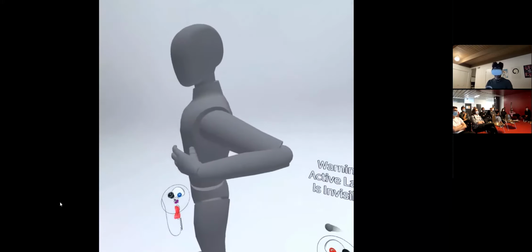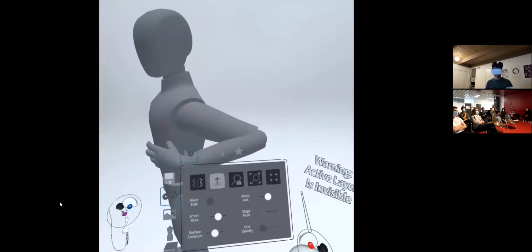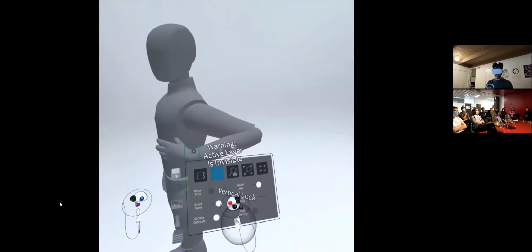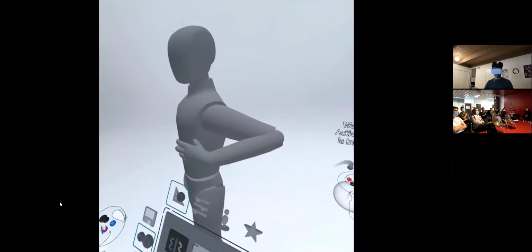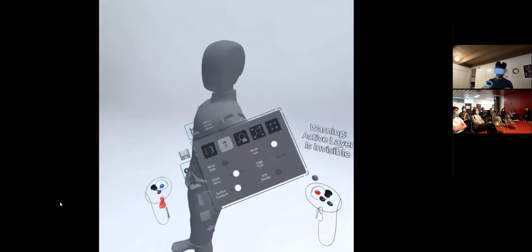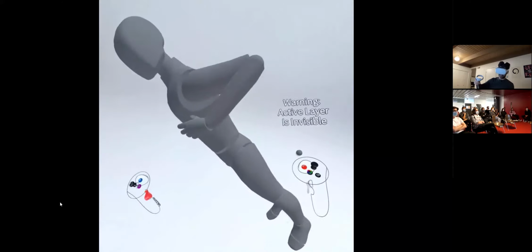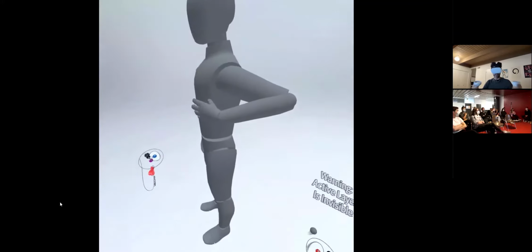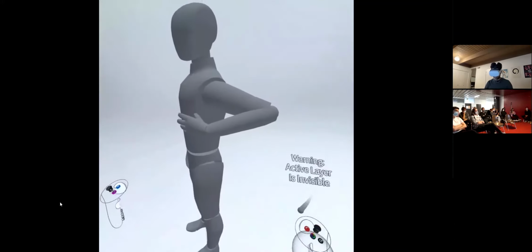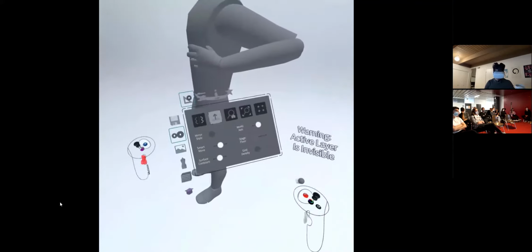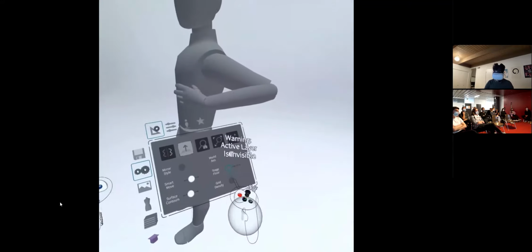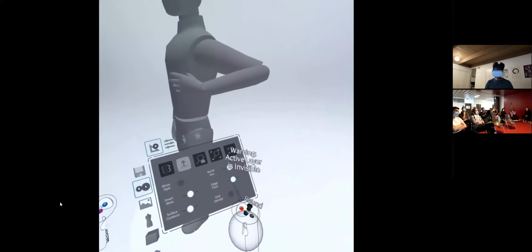So a few things I want to say about setup is I really recommend having your vertical lock on when you're doing anything in here that you're going to be moving around quickly. If you don't, it's really easy to become disoriented and have the floor be above you, and that can induce some dizziness. So if you're going to be designing an object for a long time, I recommend just having this on. If it's something that's going to be grounded, the world axis and the stage floor are important. I'm going to turn that off for now.